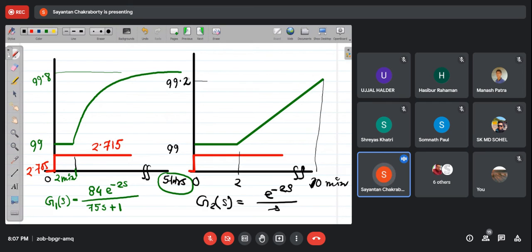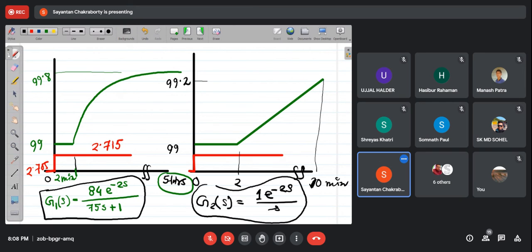So from that data, what you obtain, the gain is 1. So instead of this first order plus time delay model that requires at least 5 hours of waiting, in only 10 minutes you can calculate the slope and obtain this model, which is obviously not an accurate representation of the plant, but still quite a good approximation. So it will give you a short-term approximation of the step response behavior of a system with a large time constant, which can be approximated by this simple integrating system.